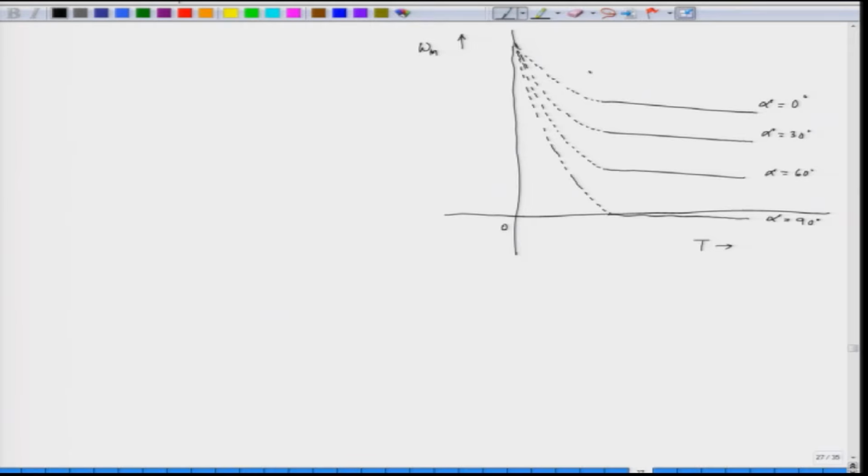And we have a boundary condition. This is the boundary. This is the continuous current operation, and this region is discontinuous current operation. And what about the no load speed? The no load speed for discontinuous current operation is given by V m by k phi.